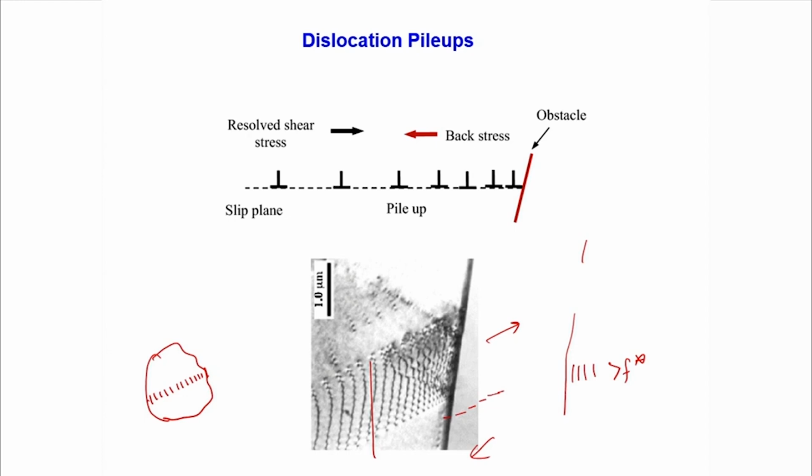So you must be thinking, one side is telling dislocations generated from the grain boundary, the other side dislocations are getting piled up at the grain boundaries. Okay, that's very simple. See, if you think of two grains like this, the fact that there are two grains means the crystalline planes are not parallel to each other. That's why their orientations are different. That's why they are called two grains, right? So now, if this is the slip plane on which a dislocation is moving in this grain 1, okay, obviously in grain 2 the same plane will not be parallel.